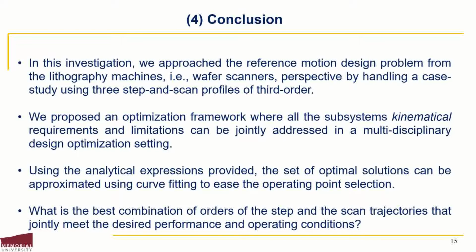In conclusion, this study covered the reference motion design problem from the wafer scanner's perspective by presenting three Step-and-Scan profiles of third order. We also proposed an optimization framework where all the subsystems' kinematic requirements and limitations can be jointly addressed in a multidisciplinary design optimization setting. To ease the operation point selection, the set of optimal solutions can be approximated using curve fitting under the analytical expressions provided. Finally, we motivated looking into the following question: what is the best combination of orders of the step and the scan trajectories that jointly meet the desired performance and operating conditions?